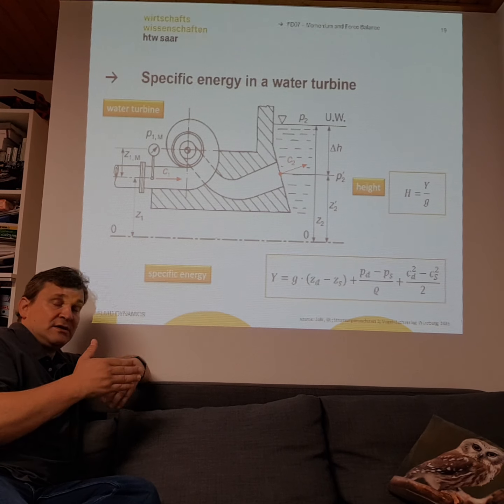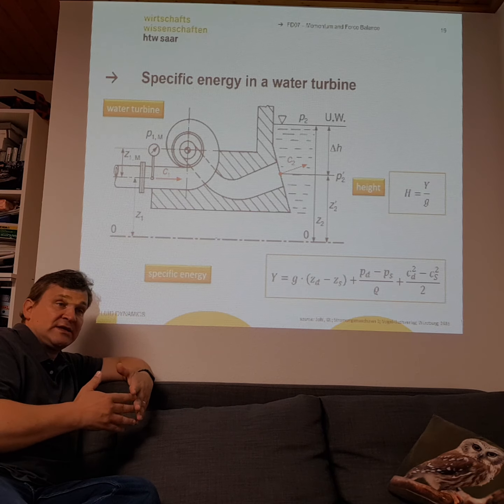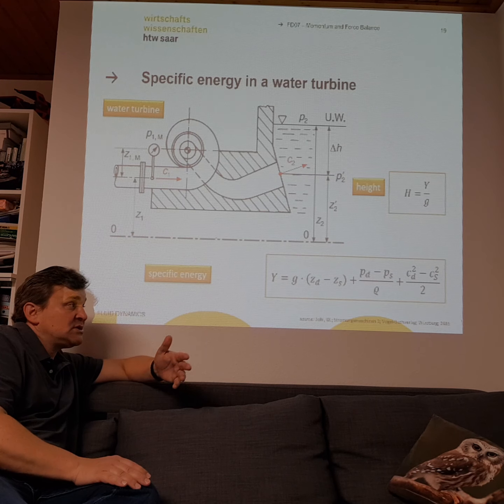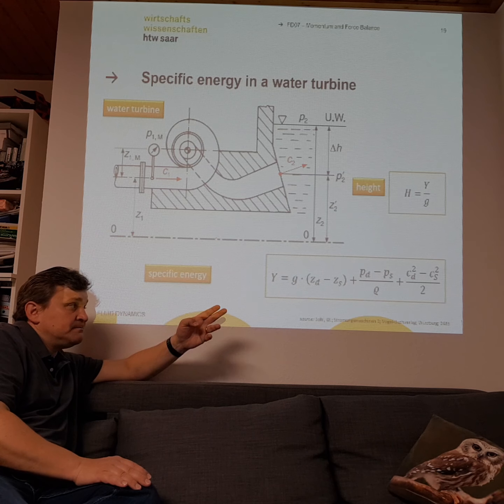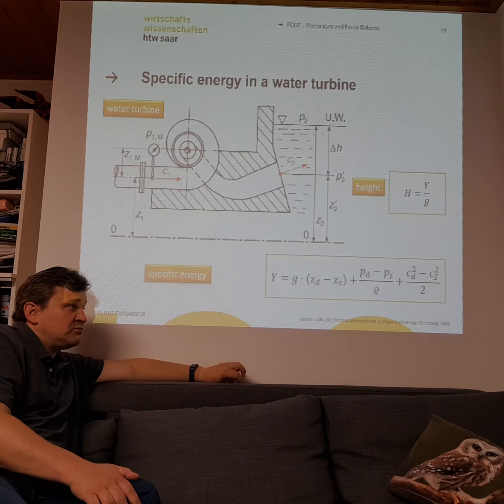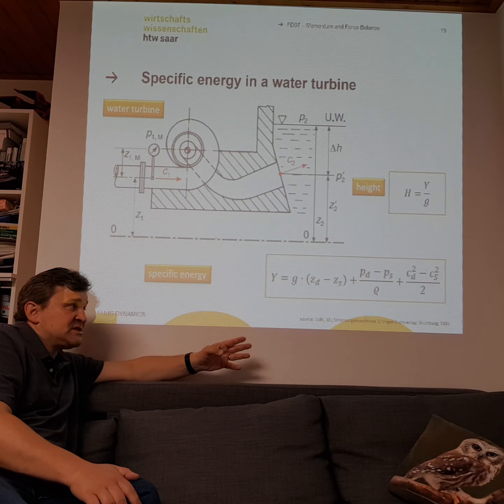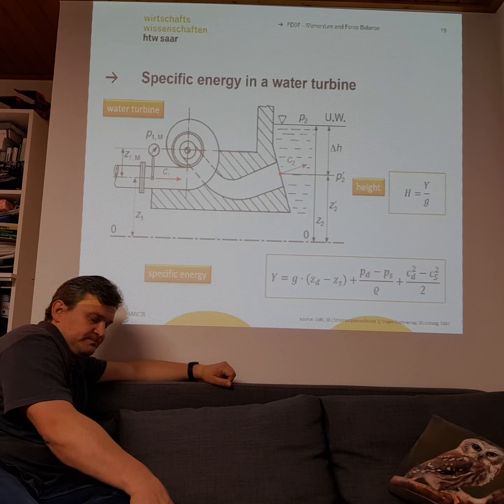And at this Pelton turbine, we can get really high height differences, about 1000 meters, and you can define your pressure difference, divide it by the density, and then you add a term of the specific energy that is based on the velocities.